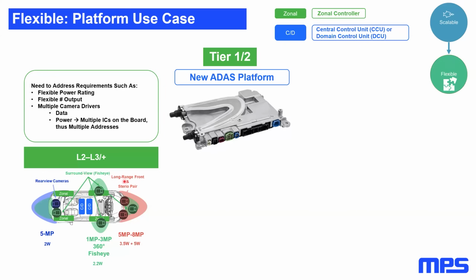To address also the high power rating, we are probably going to need multiple ICs on the board, which means that we need to interface them. And here, an analog interface on the camera switch is not the best solution because of all the necessary peripherals on the MCU, the ADC, and all the challenges coming with that: the consumption, the resolution, and everything related to that.